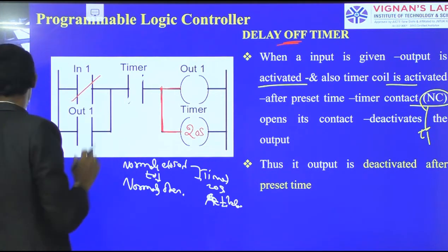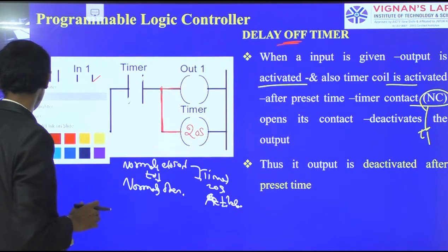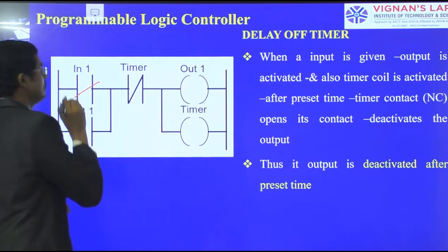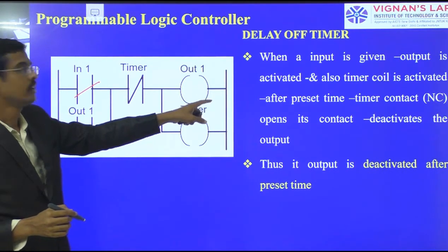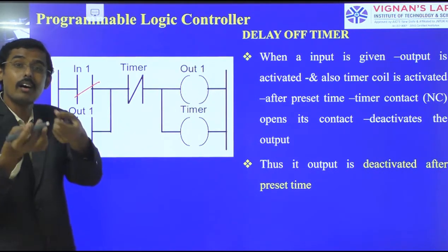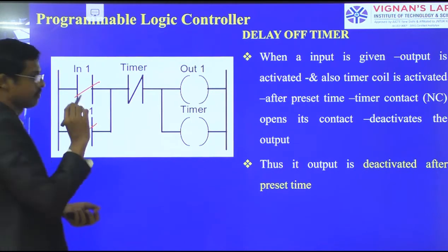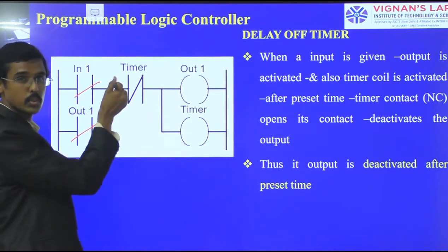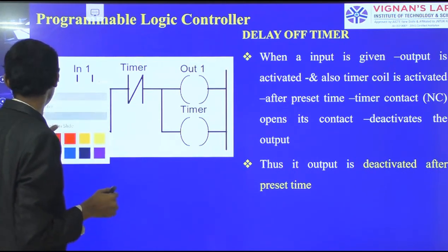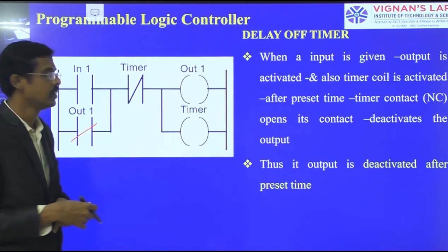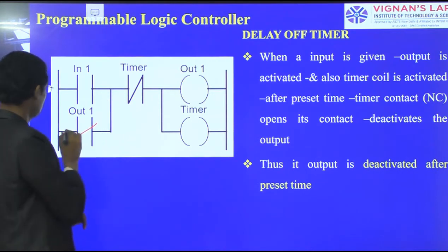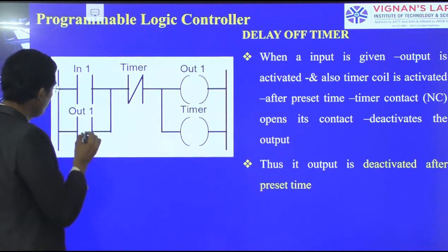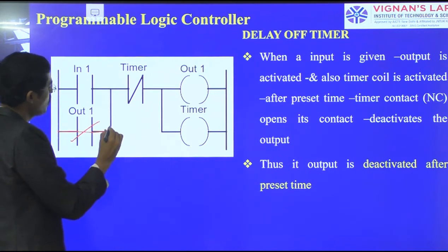In this setup, I want to tell you, even when this is connected, it activates output 1, activates the timer and also activates output 1 here. Even if the start button is a switch, let's consider this as a push button. Even if the start push button is not activated, the output 1 is latched here. See, the latching process keeps it moving. The latching process is going to make the contact here. So it will keep on moving in this way.